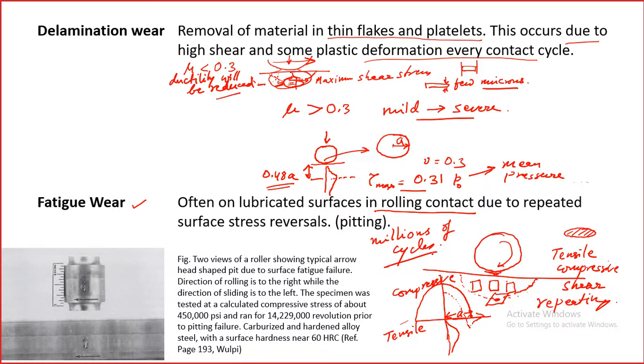So for this kind of wear, fatigue wear, there is no such thing as limiting stress. That means if we reduce the stress, it will not fail by fatigue wear, but this will not happen. At whatever stress you are working, fatigue wear will always take place.